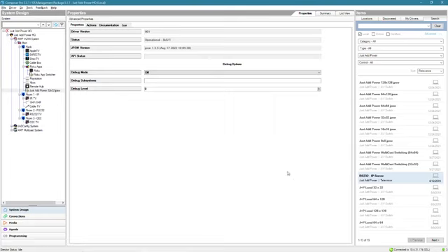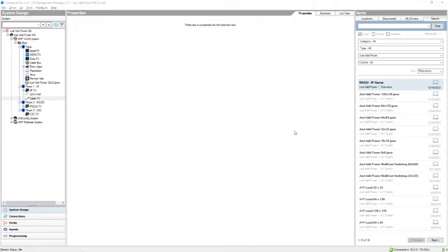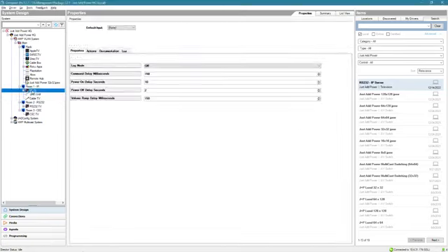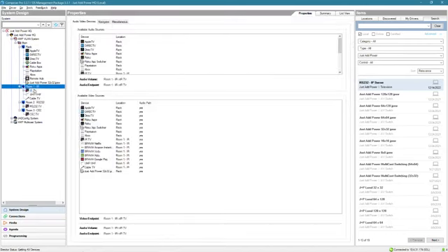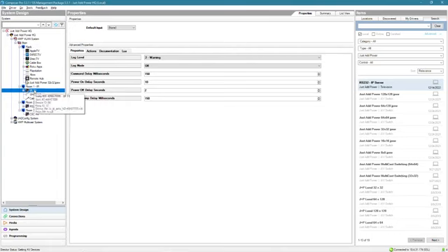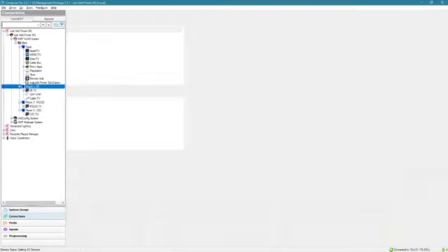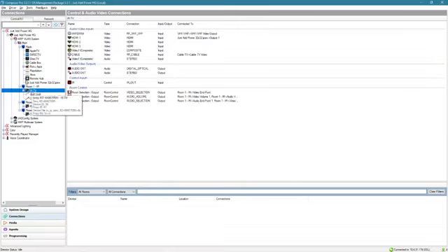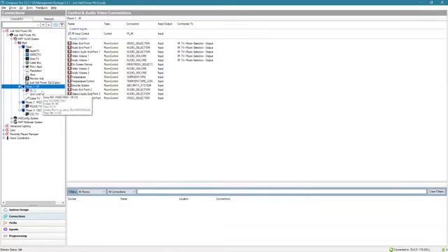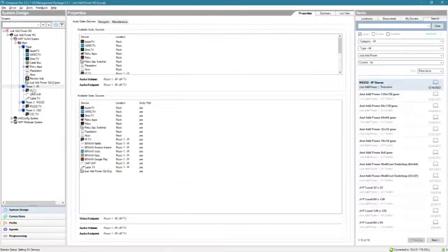We'll start with controlling a display over IR. The first thing to do is to add the driver for the actual television in the room to the room in your project. That causes the driver that you add first in connections to actually show up as the video and audio endpoint. This triggers what commands get sent. So we need the IR commands from the driver to pass through. So we've got that added, it's connected properly.